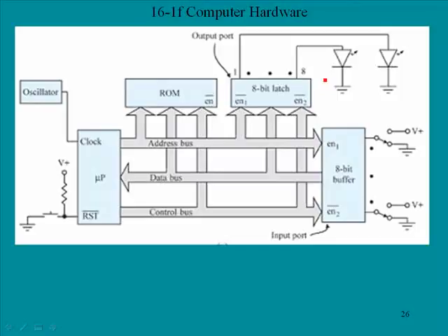However, since the PC program counter came up in a random state, the address that is being output is wrong, and the information being returned is of no value. Therefore, when the microprocessor attempts to execute the retrieved instruction, no one knows what will happen. As you can see, the microprocessor is running uncontrollably and serving no useful purpose.